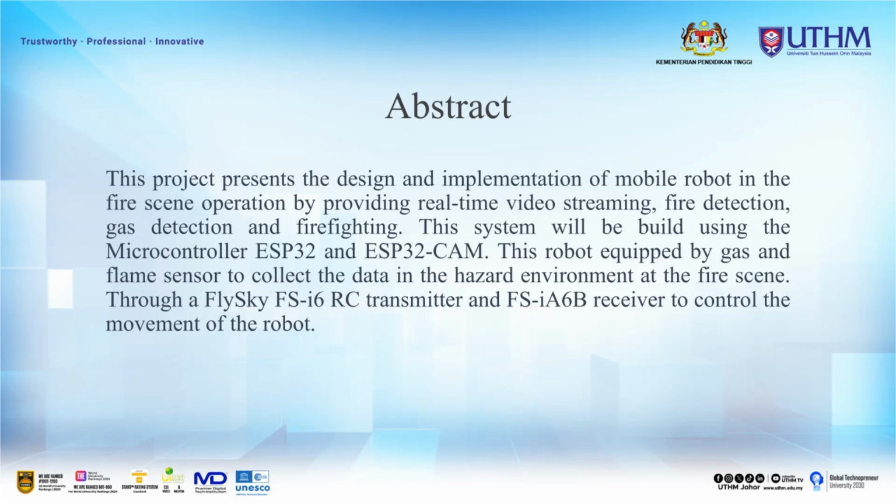First, abstract. This project presents the design and implementation of a mobile robot for fire scene operation by providing real-time video streaming, fire detection, gas detection, and firefighting. This system is built using an ESP32 microcontroller and ESP32 cameras. The robot is equipped with a gas sensor and flame sensor to collect data in the hazardous environment at the fire scene. The FlySky remote control, with transmitter and receiver, controls the movement of the robot.